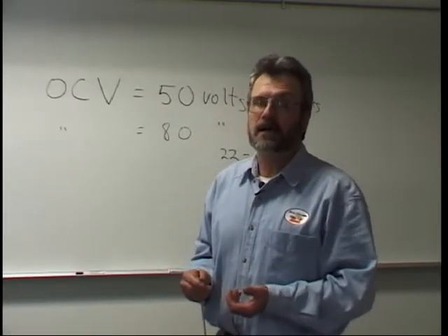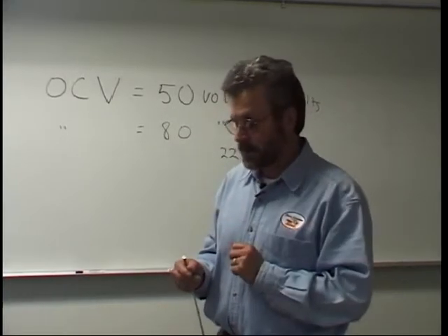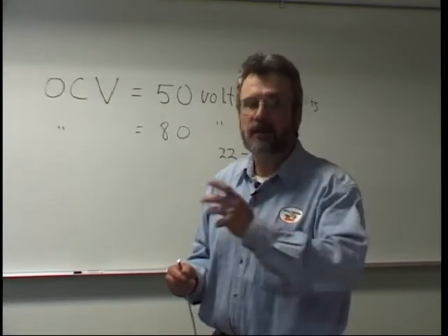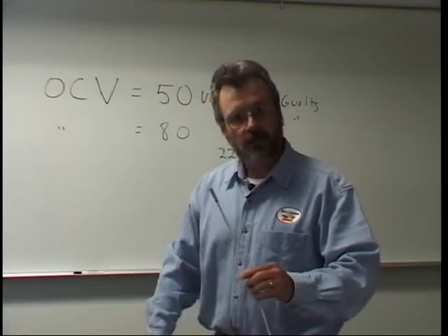You also want to match the size of the rolls. We talked about rolls a minute ago. You want to match those rolls to the size of the wire that you're using. Also, the guides that are in that wire feeder have to be matched to the size of the wire that you're using. So these things will get clogged up after a while.